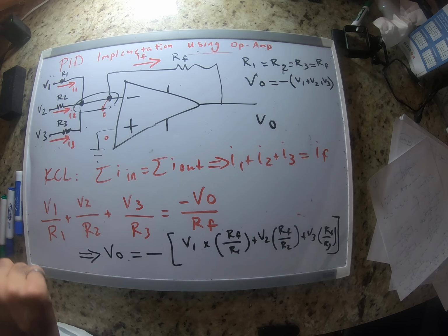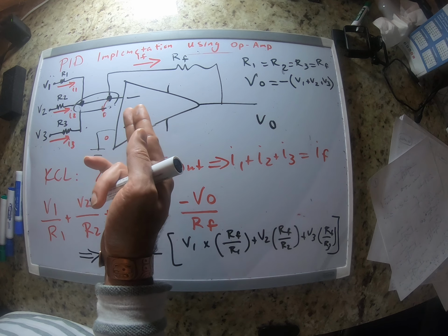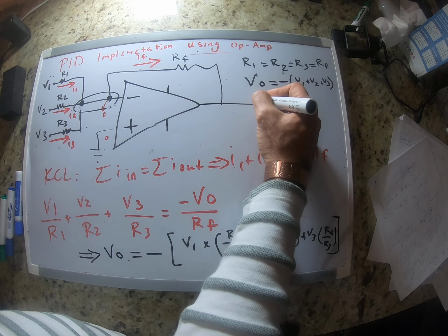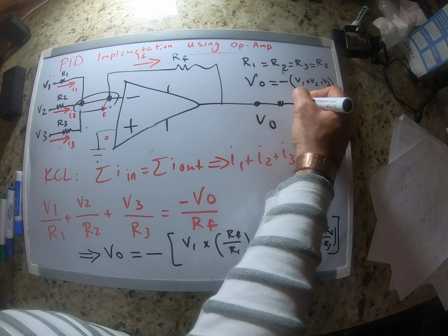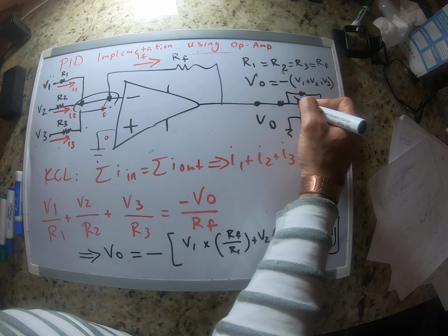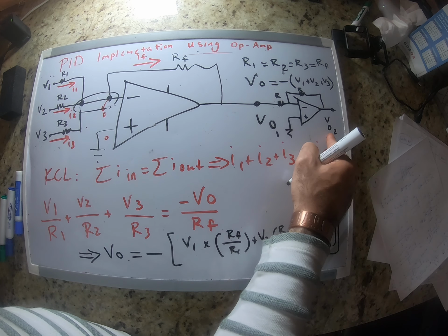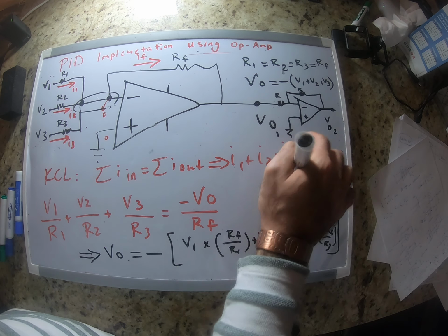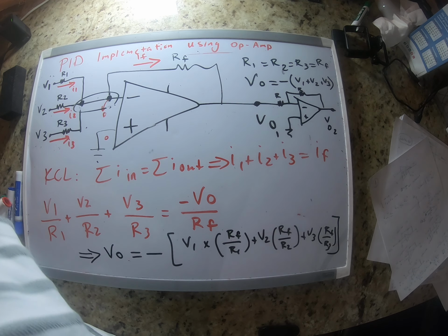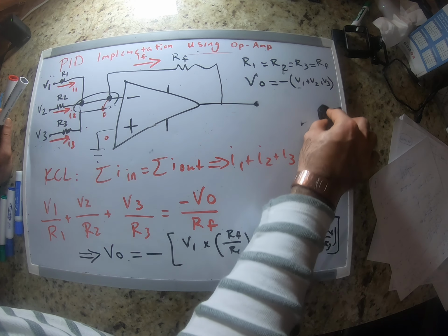input voltages. So if you want to make this positive, you can use an inverting amplifier, right, with the coefficient of 1 to make this positive, right? So let's say if I add an inverting amplifier like this here, that this is grounded, negative, positive, if these two are the same, this voltage VO1, VO2. VO2 is negative of VO1. So you can cancel this one if you cascade this somewhere with an inverting amplifier with the coefficient of 1, or actually negative 1. Okay, but that wasn't what I wanted to discuss right now.